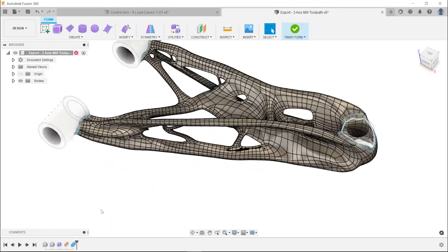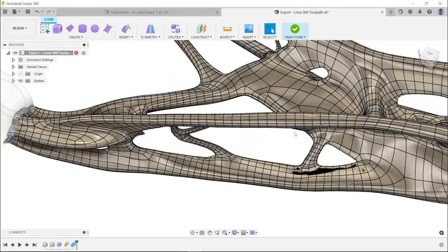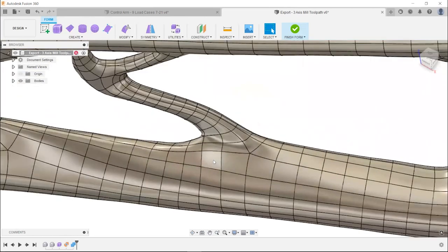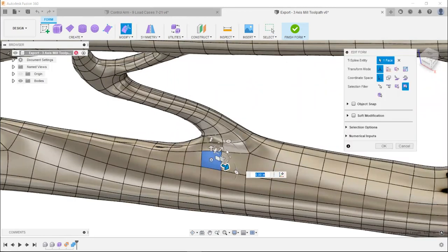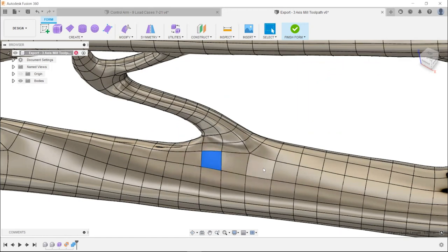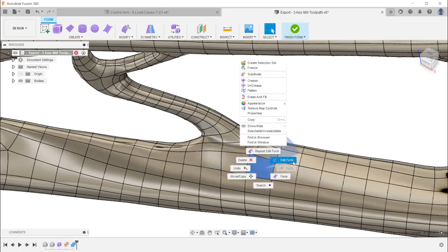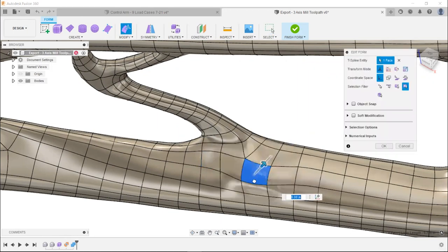So let me just get into the T-spline area. So the T-splines, basically, as you can see here, this is how we connected our preserved geometry. So for example, if you wanted to make an edit to that, you can grab faces, edges, points, and you can pull them out. And in this case, I'm not sure what I did. I rotated it. So let's do this one. So you can see, you can pull it, drag it.